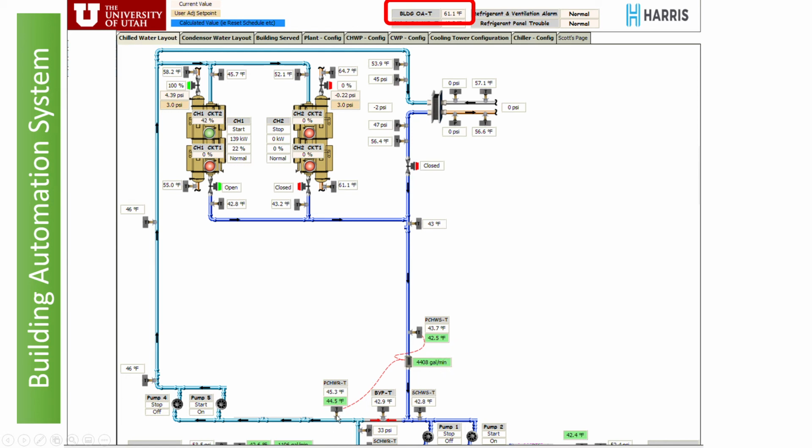So there's a temperature sensor here, connected to, this is a flow meter. This is measuring water flow in the pipe. So 4,408 gallons per minute is being pumped through this pipe and measured right here by this device. And then this is another temperature sensor. So this is essentially supply and return temperature readings with a flow measurement. So from a temperature differential and a flow, you can calculate BTU. And I'll show you what that instrumentation looks like in the field. It's kind of cool.